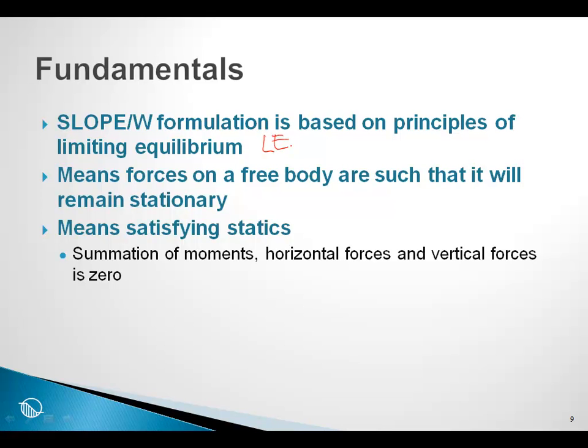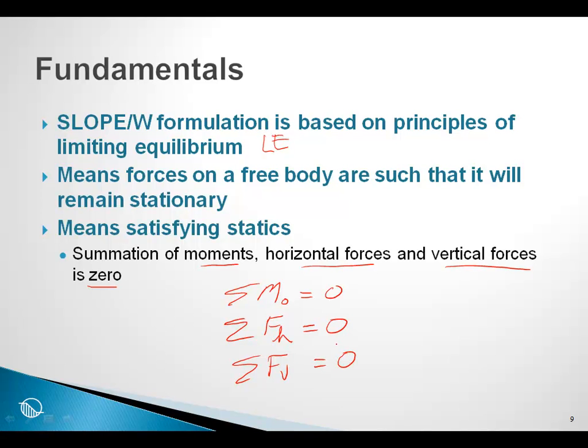It means the summation of moments, horizontal forces, and vertical forces must be zero. So the summation of moments about some point must be zero. The summation of forces in the horizontal direction must be zero. And the summation of forces in the vertical direction must be zero. This is at the heart of a limit equilibrium formulation.